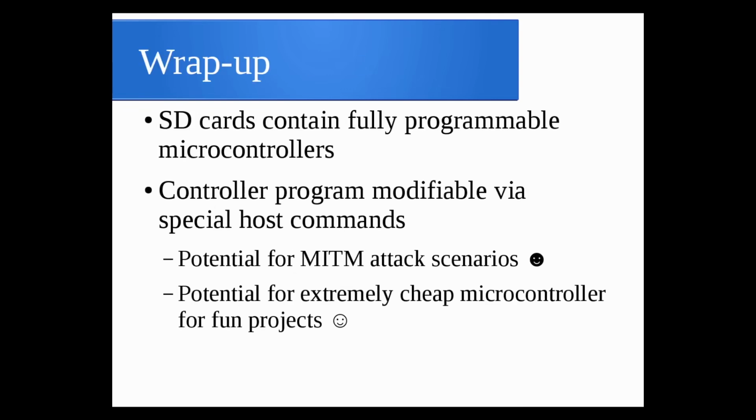So, to wrap up, SD cards and any sort of flash type memory will contain a fully programmable microcontroller, perhaps a very powerful microcontroller. This applies to SD cards, micro SD cards, eMMC, SSD, USB controllers. The controller program we have demonstrated is modifiable via special host commands, and these are typically not locked out because of the complexity of the flash memory space.